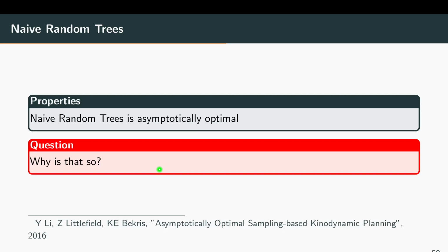But why was it not the case with regular RRT? What is the difference here? I think the problem is that with regular RRT, we might initially have a suboptimal path, but this will never get corrected, right? Exactly. I don't know if we had an example, but basically for the original RRT, the Voronoi bias that helps us exploring also sort of prevented us from doing anything optimal. Right, so maybe I do a more extreme example.